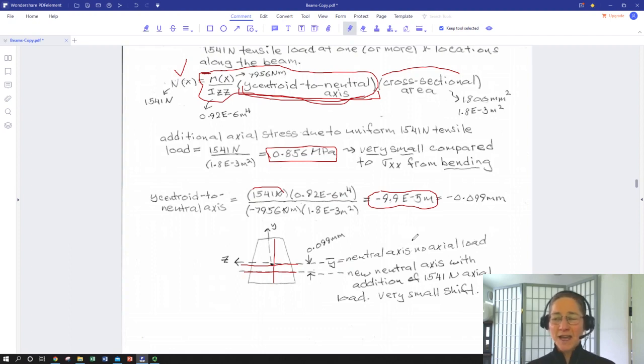Because as you can probably guess, if you're looking at a big beam in flexion, a lot of materials cannot tolerate tension, and so you'll be using a composite where one of your components is very capable of supporting tension, and so you're going to want to put all of that pretty close to where your max tensile axis is.